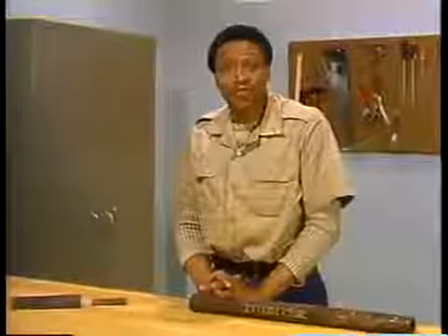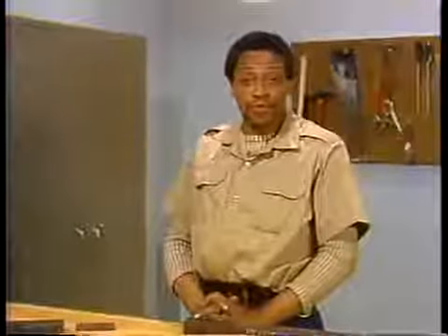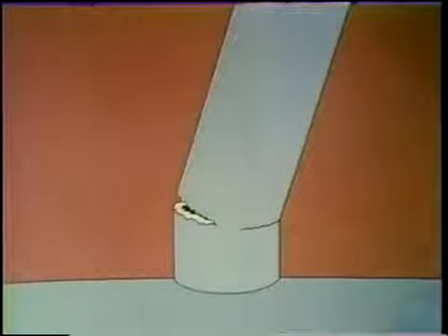Vibration sets up another kind of mechanical stress. The flow of water or steam through a tube and the flow of hot gases around a tube can sometimes cause vibration. We've exaggerated the vibration to make it easier to see. As a tube vibrates, it bends back and forth over and over again. This repeated bending can cause the tube metal to crack. This is called metal fatigue.